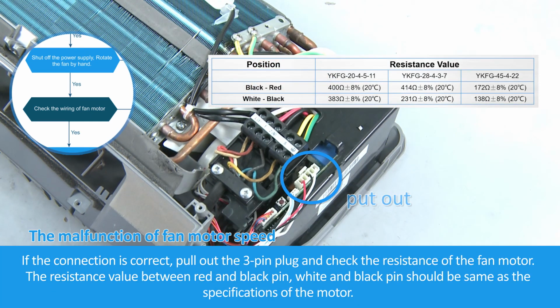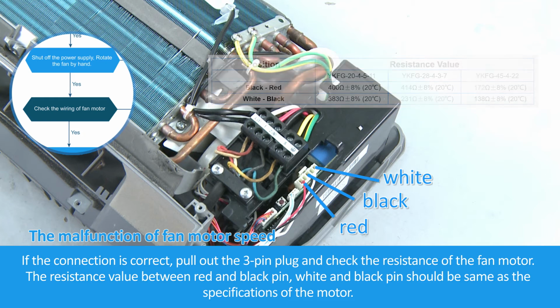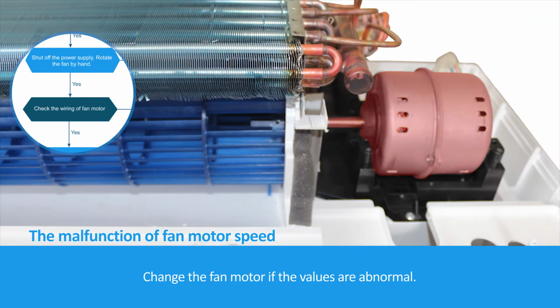If the connection is correct, pull out the 3-pin plug and check the resistance of the fan motor. The resistance value between red and black pin, white and black pin should be the same as the specifications of the motor. Change the fan motor if the values are abnormal.